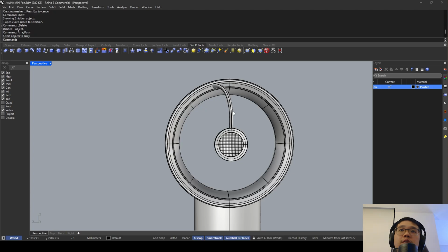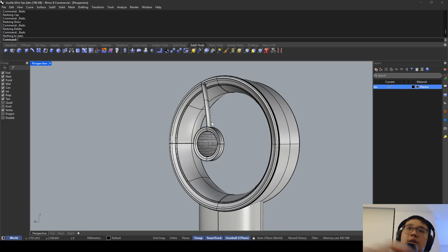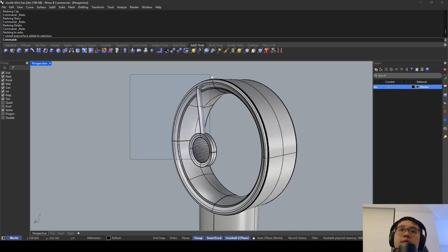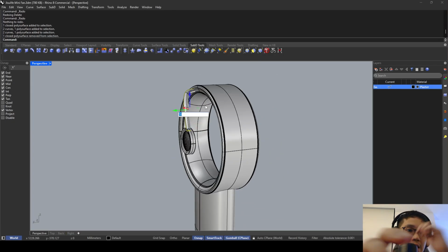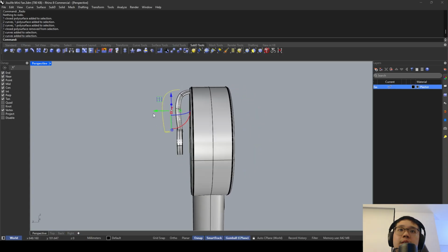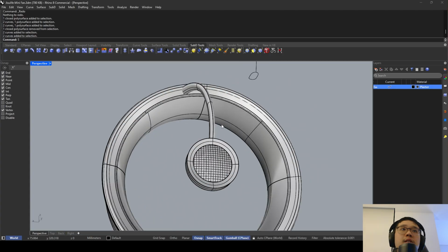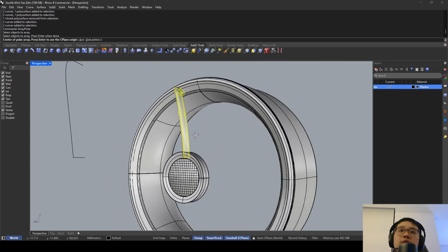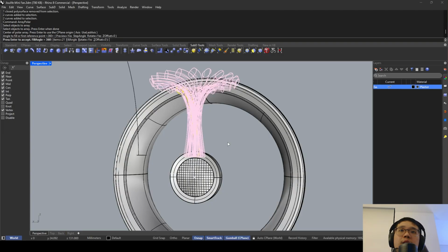So now I can array polar. Hang on. Did I just delete off? Okay. I will just bring this out by 10 mil because I want to keep that. That is important. I'll bring it out by 40 mil, so the total is 50 mil. So I have a copy of this. Array polar, object to array, center here, I guess.